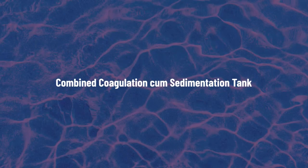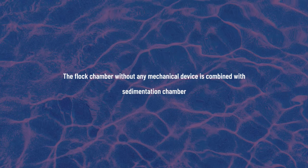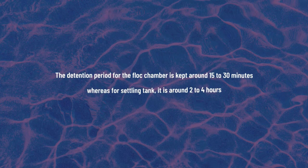Combined coagulation cum sedimentation tank. Putting the mechanical part in the system makes the system cumbersome and expensive also. Flocculation tank is sometimes combined with sedimentation tank to make the system economical. The floc chamber without any mechanical device is combined with sedimentation chamber. The depth of the floc chamber is kept around half that of the settling chamber. The detention period for the floc chamber is kept around 30 to 50 minutes, whereas for the settling tank it is around 2 to 4